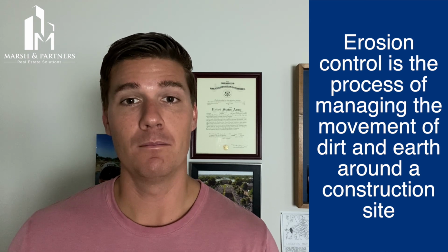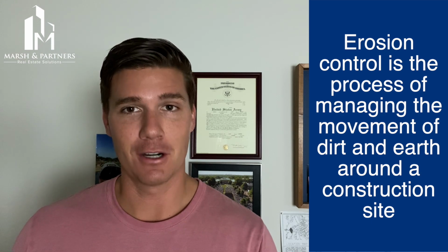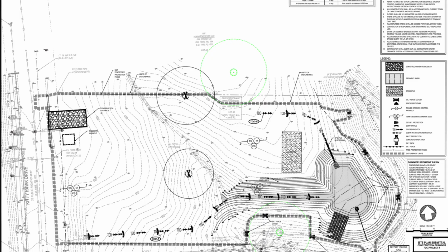Now, one of the most important aspects of the engineering construction drawing plan set is the erosion control plan. Erosion control is the process of controlling the movement of dirt and earth around a construction site. As land development occurs and infrastructure is installed, dirt is displaced as a result. Water pollution and reduced soil quality are big problems that result from poor erosion control. So to combat it, a civil engineer needs to come up with temporary erosion control plans for various phases of construction. Those construction documents will even show more details for temporary measures, like diversion ditches, sediment basins, outlet areas, etc.